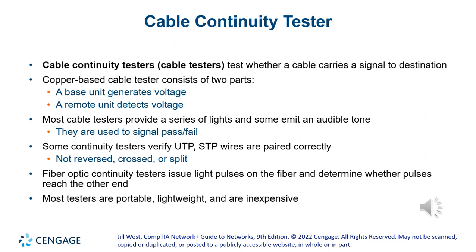Some of them will actually tell you the length of the cable, so you can test it from end to end, and it will tell you based on the trip time how long the cable is. A very, very close estimate if it's a 6 feet, 10 feet, 20 feet cable, something like that. That's how you can test a cable to make sure that you didn't go beyond the 100 meters. They also have similar tests for fiber optics.